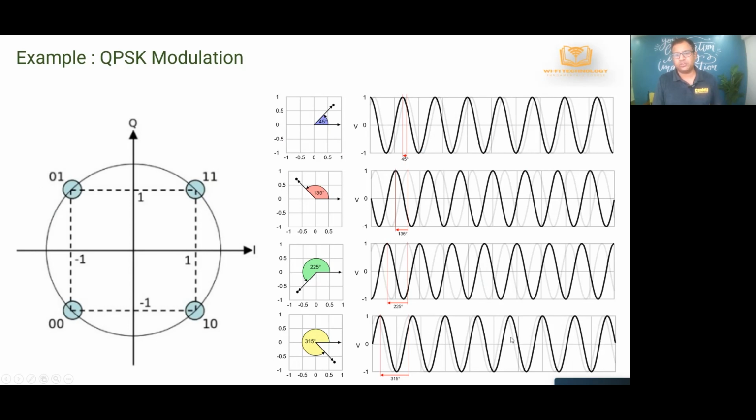So you're not changing frequency, you're not sending anything faster. One thing to remember here is that when you're sending information, the speed at which the waves move from the transmitter to receiver never changes, right? The signals still travel at the speed of light. So the speed at which the signal is transmitted from here to here does not change. What changes is how much information you're carrying on that signal. And the more information you carry in the signal, the higher the data rates and the more the throughput.